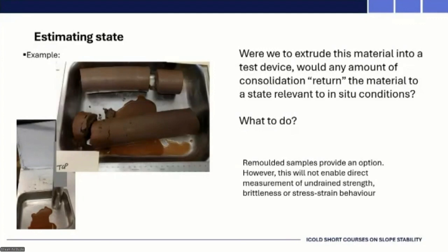When you dug down a bit, the reason they were saying that is because lab tests were reconstituted with a little bit of compaction, a little bit of densification. Otherwise, the samples didn't stand up. They fell over. So people were making it dilative in order to test the strength, without thinking through all this critical state stuff. And that was prior to the Jefferies and Been book, et cetera, et cetera. So if you're going to do reconstituted samples, you want to try and get to a void ratio that is similar to what you think is in the field. But how to get there with less cohesive materials?